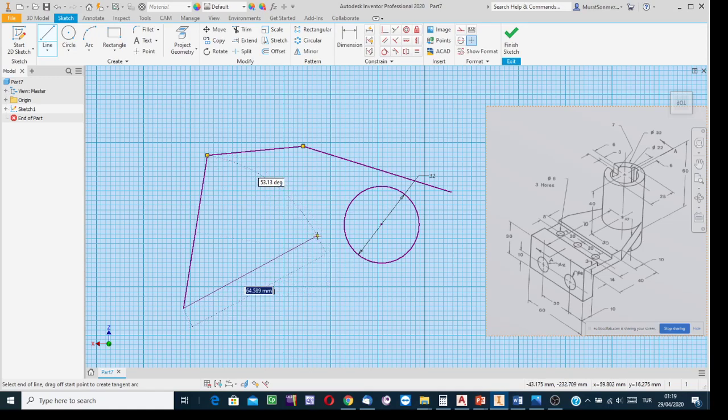Because if there is a dotted line, for instance here, when the cursor is at this position between the midpoint of this line and the cursor, this dotted line means if I indicate this point as the terminal point of this line, then that point and the midpoint of the other line will be geometrically related by the software.